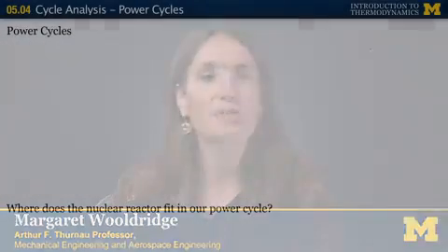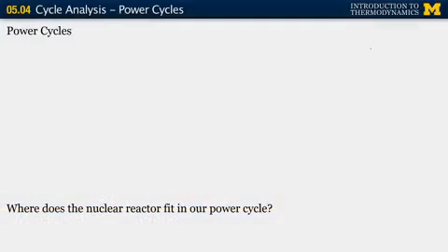There are essentially 3 categories of cycles, and it's more like 2 categories because 2 of them look a lot alike. In power cycles, the goal is to actually generate power, or a rate of work transfer out of the cycle. The other flavor of cycles are refrigeration and heat pump cycles. The goals of those cycles are actually to move heat around, to provide a particular type of heat transfer rate. So under the power cycle category, our goal here is to provide net work transfer to the surroundings.